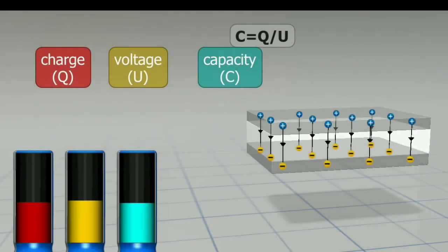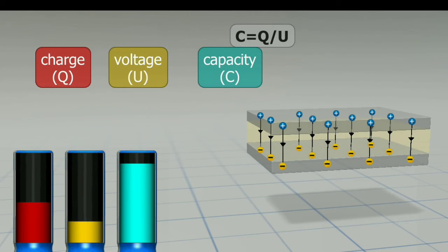The relative permittivity of polyethylene is 2. That is, using polyethylene as a dielectric allows the capacitor to store twice as much charge as it could store if there was air between the plates. If there is paper between the plates instead of air, the capacitance will be more than triple, since the relative permittivity of paper is 3.5.